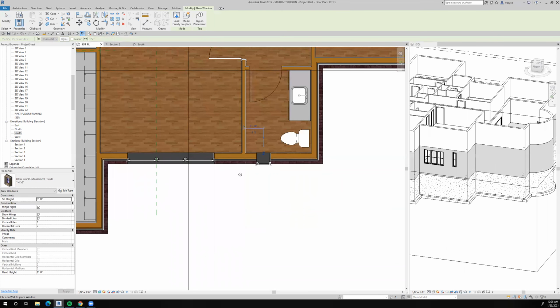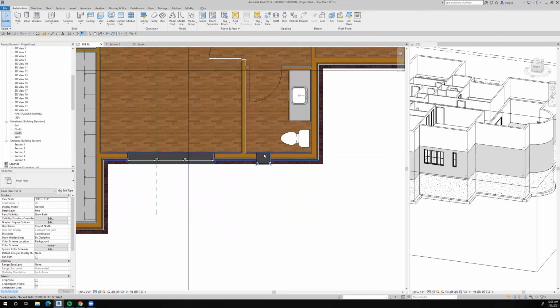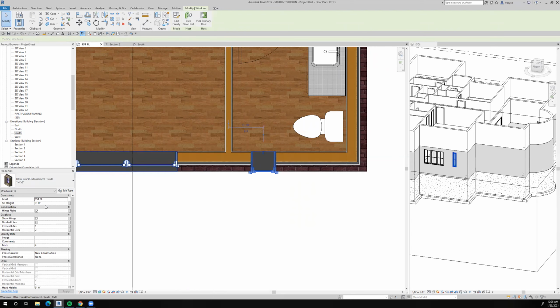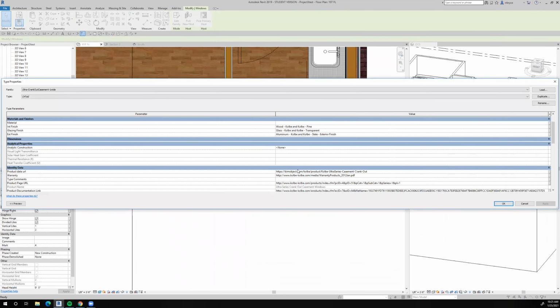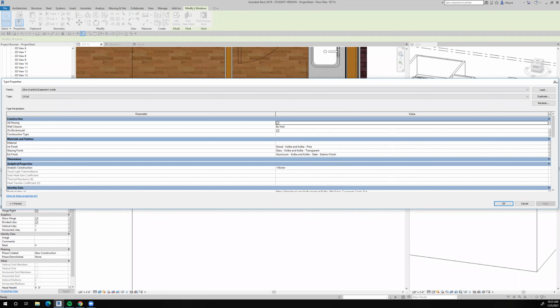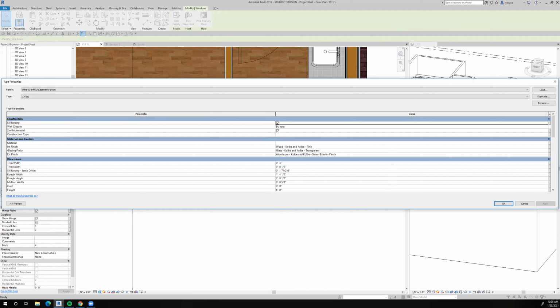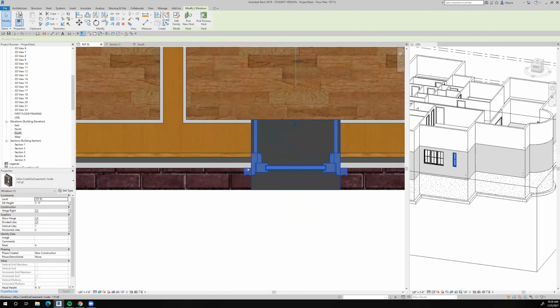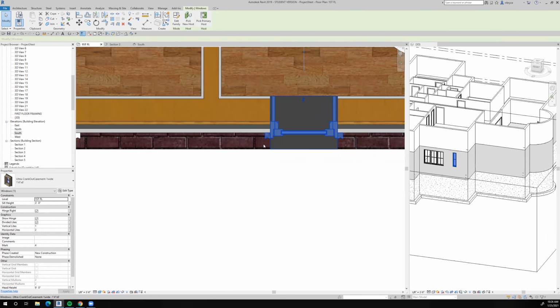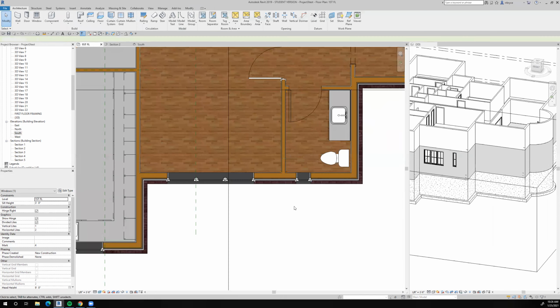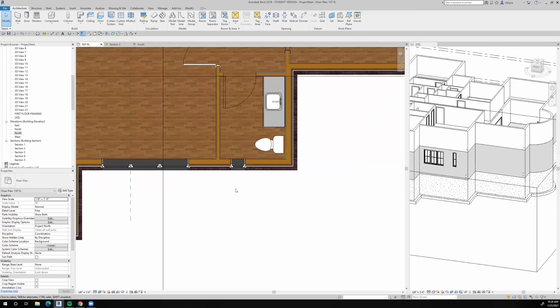It's pretty narrow. And it should be recessed by 4 inches. So let's go back, edit the type. The brick mold, the inset's going to be 4 inches. So the brick mold will be at the wall, the sheathing, not at the brick itself. Minor detail, but see, the brick mold really sits here. And then Colby hasn't cut the window correctly because the brick would stop at the outside face of the brick mold, but for purposes of this demonstration, that's okay.